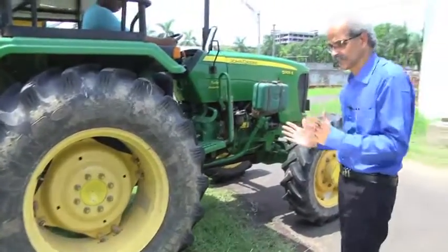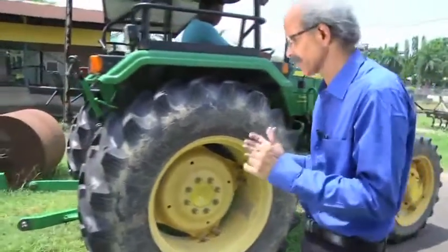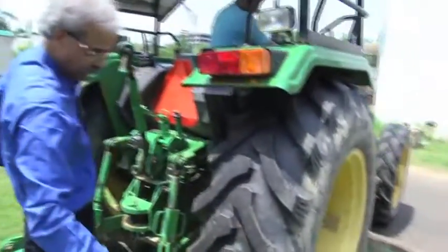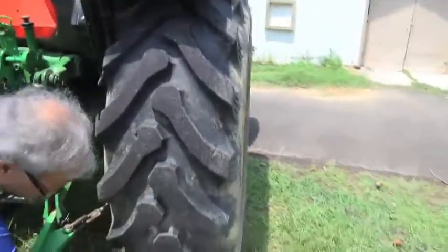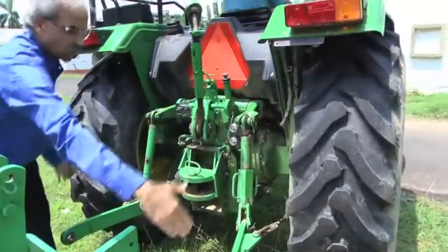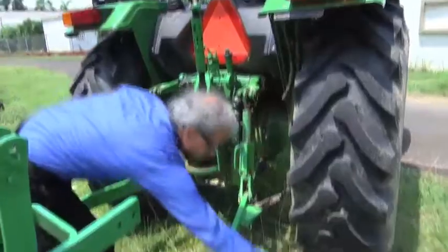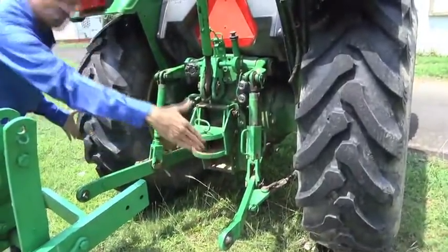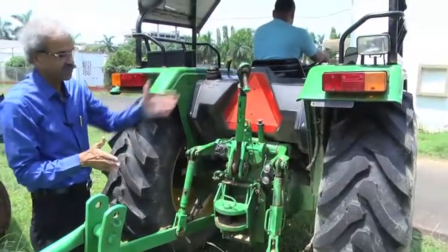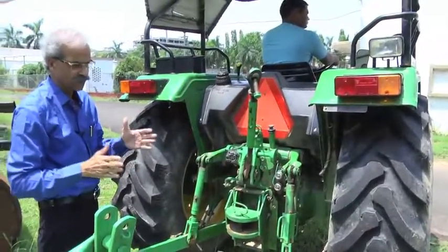And wheel tread is another thing which is important so far as the tractor is concerned. Now, wheel tread is the center to center distance between the two rear wheels as well as the front wheels. This is called wheel tread, and which I showed there, the center to center distance between the front and rear wheels is the wheel base.